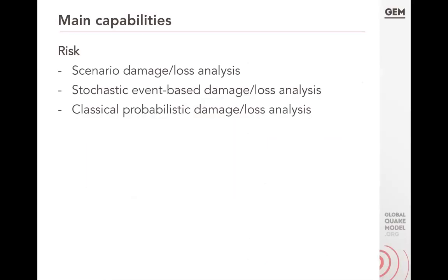On the risk side, again, the capabilities are similar to what I showed on the hazard. So each of the hazard calculators can be linked to exposure and fragility and vulnerability models to go forward into damage and loss analysis. So the scenario hazard calculators could be linked with fragility and exposure models to be able to run scenario damage and loss analysis. And then similarly with the probabilistic calculators, you can do probabilistic damage and loss calculations.